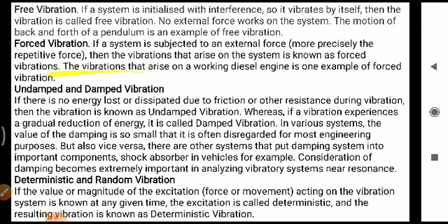The next classification is damped and undamped vibration. Damped means the vibration is reduced with the help of some medium. Normally we will be giving oscillation to a simple pendulum. The pendulum oscillation is diminished or reduced because it is kept in the atmospheric air. And suppose we keep the pendulum inside the water.